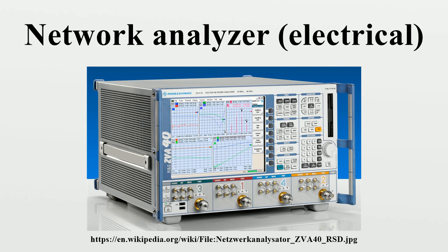For the VNA, the receiver measures both the magnitude and the phase of the signal. It needs a reference channel to determine the phase, so a VNA needs at least two receivers. The usual method down converts the reference and test channels to make the measurements at a lower frequency. The phase may be measured with a quadrature detector. A VNA requires at least two receivers, but some will have 3 or 4 receivers to permit simultaneous measurement of different parameters. There are some VNA architectures that infer phase and magnitude from just power measurements.